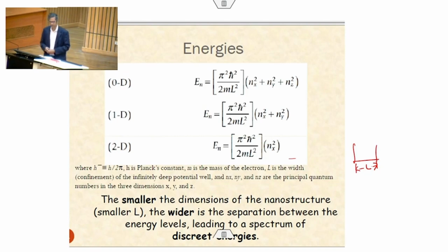So, in bulk homogeneous solid materials, the wavelengths of the phonons and the electrons will be much smaller than the length of the material, or rather the length of the microstructure. Let us talk about microstructure, because the length of the material may be different, but the grain structure or microstructure is what is very important. So, in a homogeneous bulk material, the wavelengths of phonons or electrons will not make any difference at all, because the length of the microstructure is much bigger than the wavelengths. But in nanomaterials, the length scale of the microstructure will be of a similar scale as the wavelengths of the electrons or the phonons. Therefore, quantum confinement is bound to take place.